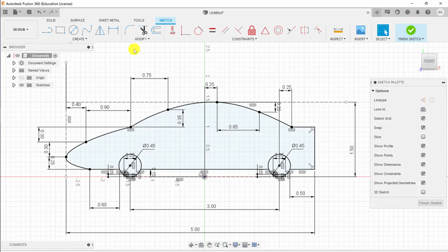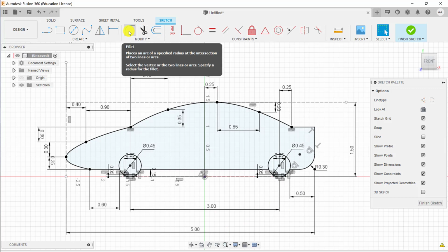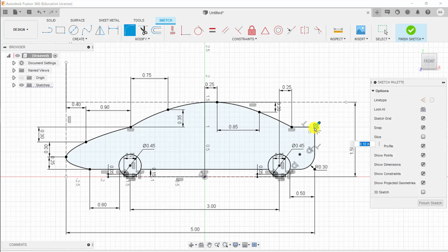and we want to make these corners rounded, so we use the fillet tool. So let's do a fillet down there for 0.3 meters. It comes up with a warning because it's mad that I basically ruined the constraint by adding a curvature there, this 5 meter constraint, but it compensates for that by adding a point there, so we should still be fine. And then do another fillet up here with 0.2 meter, and there we go. That is our generic car body shape right there.